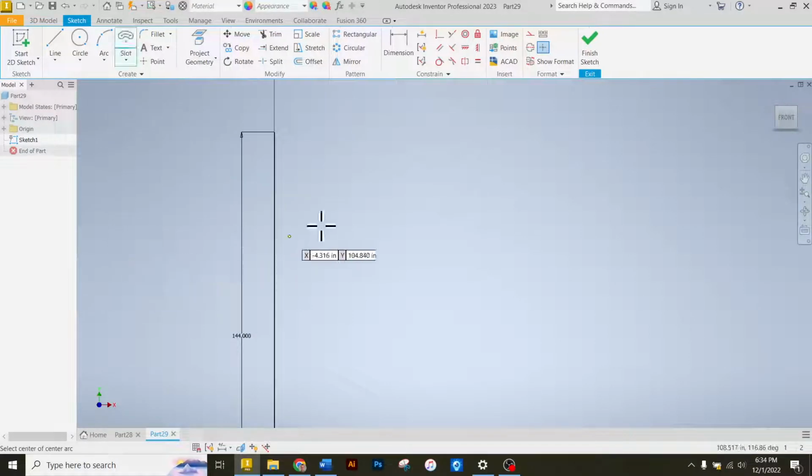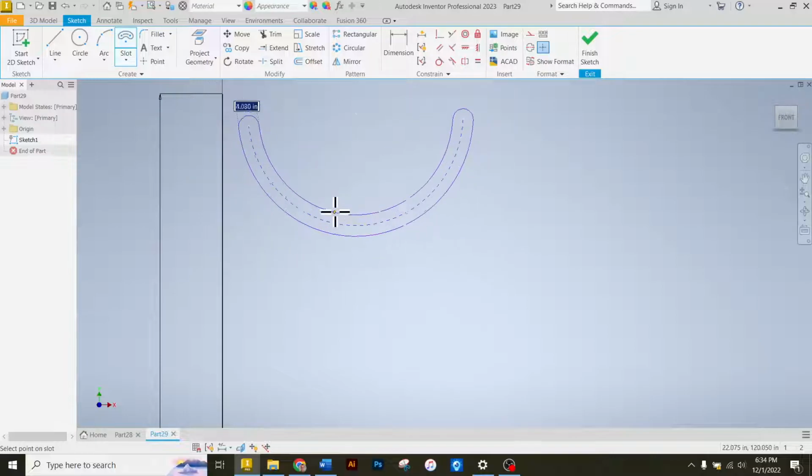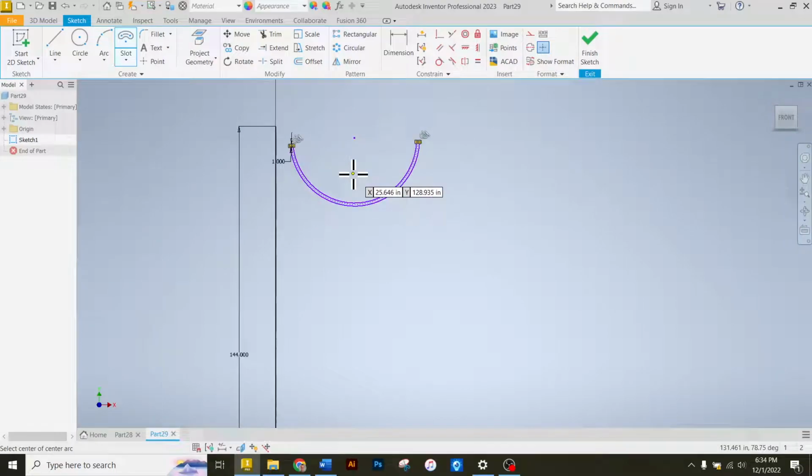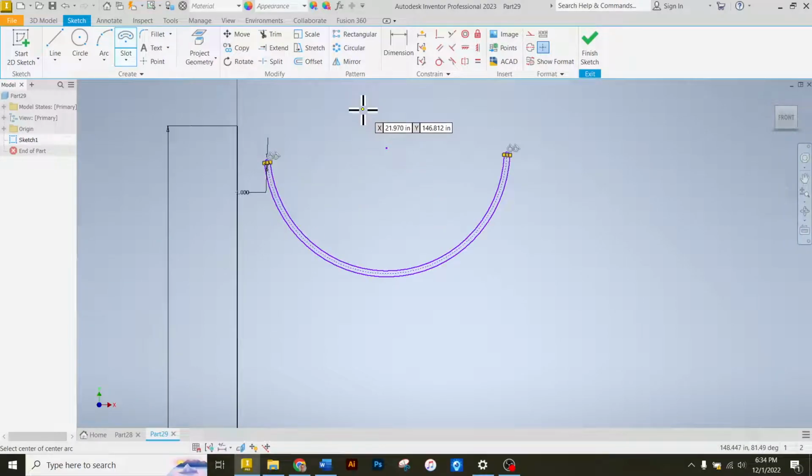So I'm going to click there, and I'm going to drop this over the side, draw this more or less like that. Right here it's going to ask me how thick I want the walls to be, and I want it to be 1 inch, so I'll use that. And now I need to define where these edges go and how far they are from this over there. So I'm going to click this dimension point and this point. It should be 36 inches.